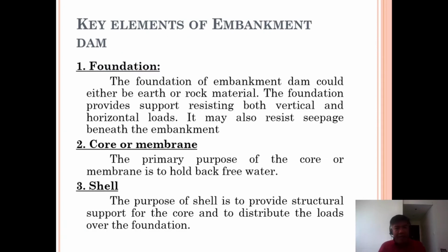So what are the key elements of the embankment dams? Number one is the foundation. That's why there is another type of analysis in the embankment dam, which is the foundation analysis. It is in the geotechnical part of the study, analyzing the bearing capacity, the uplift pressure, and the stress and strain of the soil.